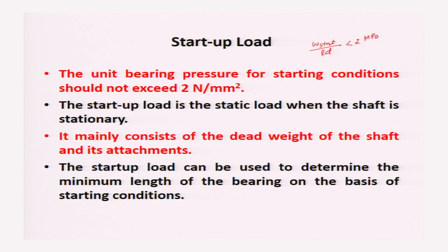The startup load is the static load when the shaft is stationary. It mainly consists of the dead weight of the shaft and its attachments. The startup load can be used to determine the minimum length of the bearing on the basis of starting conditions.